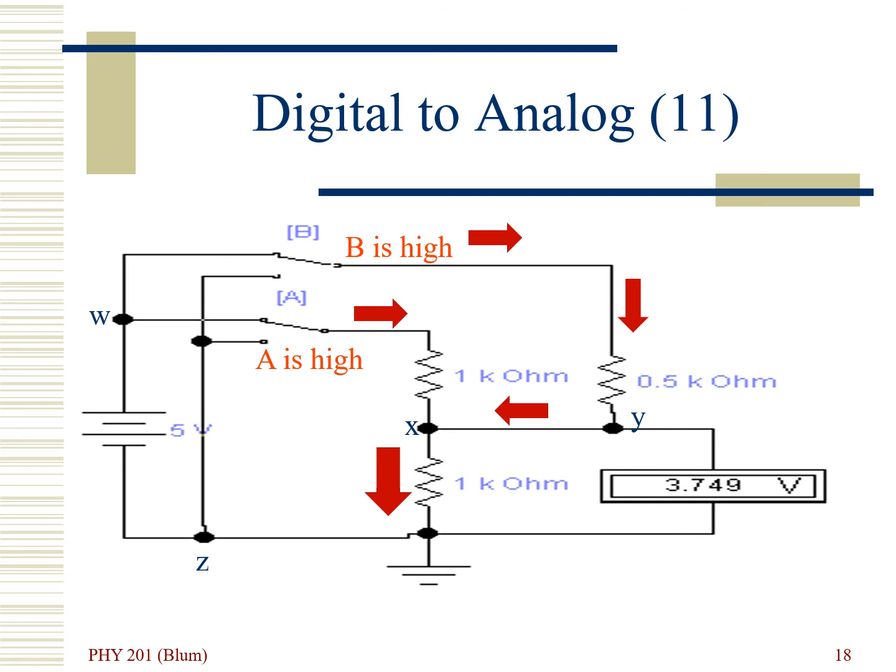And those two currents are combining at junction X and then going through the lower 1 kilo ohm resistor. So the upper 1 kilo ohm resistor and the half kilo ohm resistor are in parallel. There's a wire connection. The XY nodes are the one side of connection, and then the upper sides of those two resistors both connect to the junction I labeled W just above the battery. So they are a parallel combination.